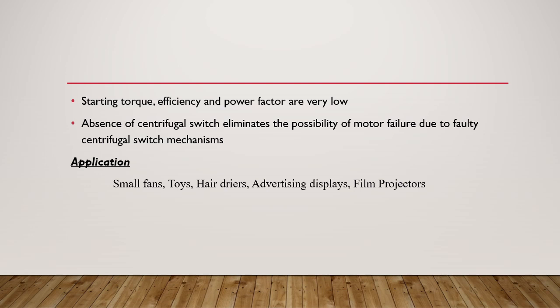The starting torque, efficiency, and power factor are very low because all these things are very small. There is no centrifugal switch. Due to this, it eliminates the possibility of motor failure due to a faulty centrifugal switch mechanism.